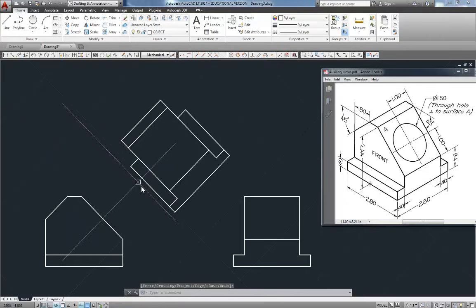And that's how those feet look when this part is, if you will, kind of tipped back, and we're looking straight at this front face. I will tell you this, if I drew a line from here, technically speaking, there's a hidden line through here. I'm not going to have you show it in class. Just clutters things up. Technically, that back corner is hiding back here as a hidden line, but we're not going to show that. Okay.